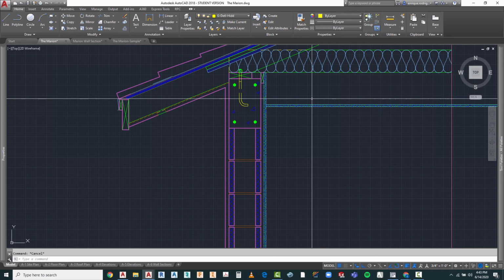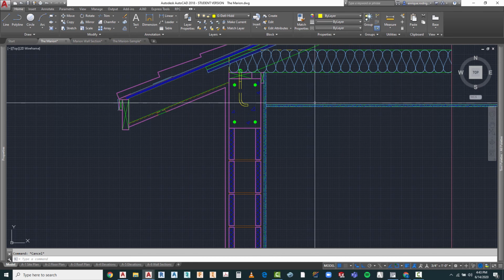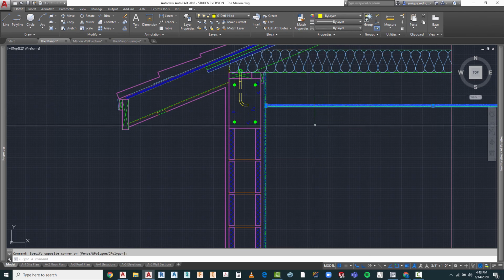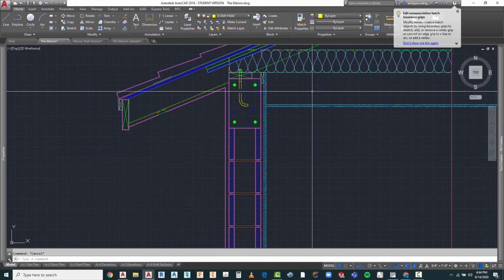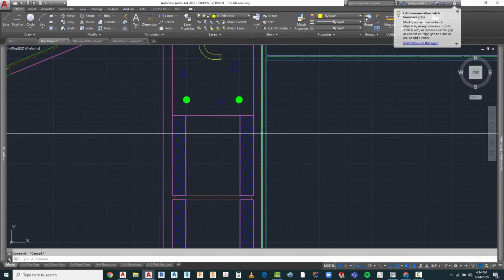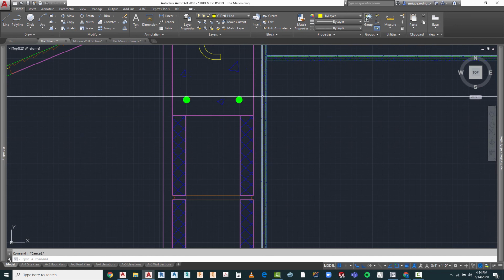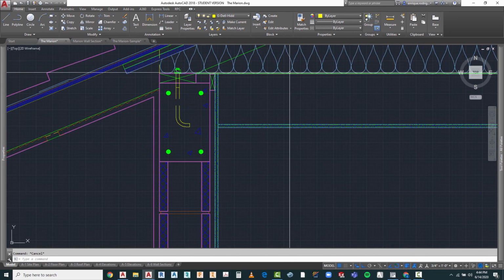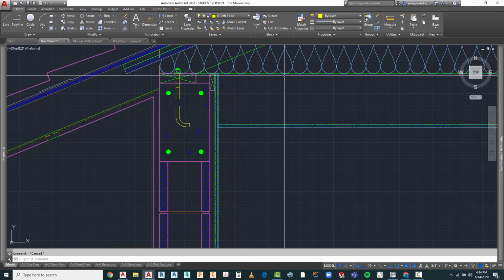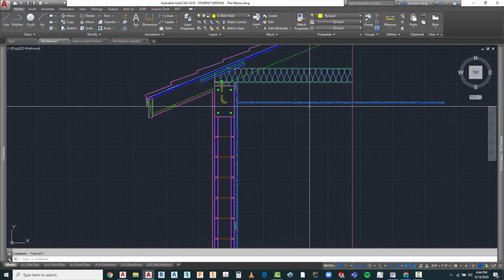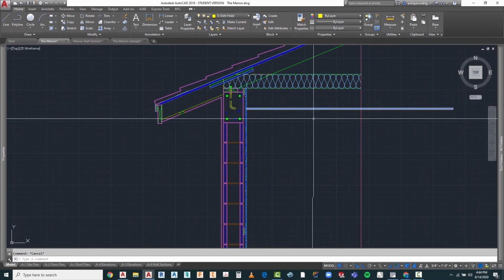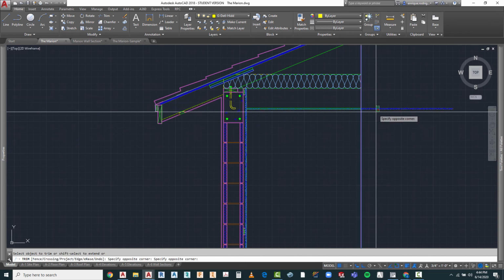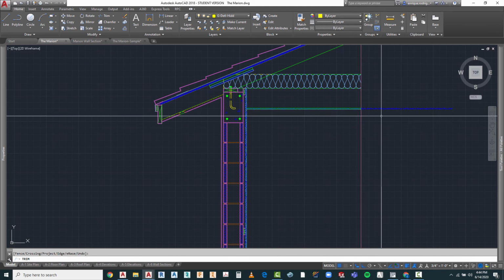When you use a 1/2 inch drywall, what ends up happening is if you attach that drywall every 2 feet, you're going to get some waviness because it's not really that thick. So in some cases, some people will go to 5/8 inch drywall. The same thing applies for the furring strips here. The furring strips vertically are at every 18 inches. You don't want your walls to be wavy. So what we need to do is apply something that we can screw our drywall into that's going to be at 18 inch intervals so that we don't get that waviness. So what I'm going to do is go ahead and trim this out for now right here. And let's do one more trim.